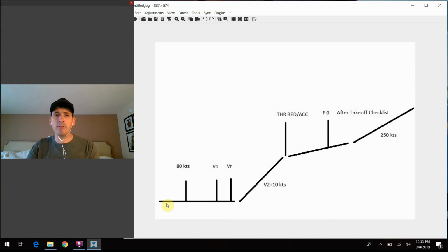We want to give the engines a chance to, like we said, get up to speed. And of course, if you go back and look at jet engine performance, they actually make a majority of the thrust between the 50 and 100% range of speeds. So that is the reason why we do that.